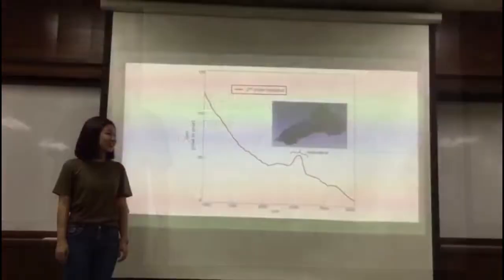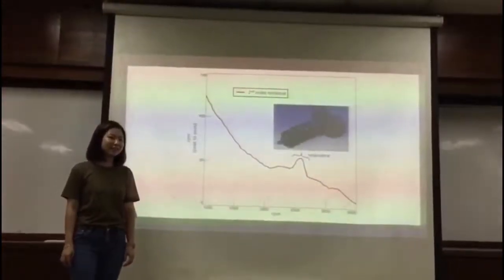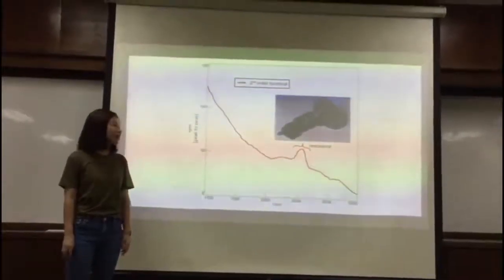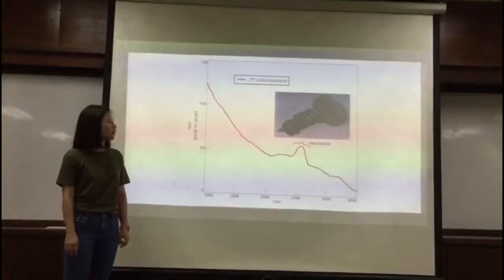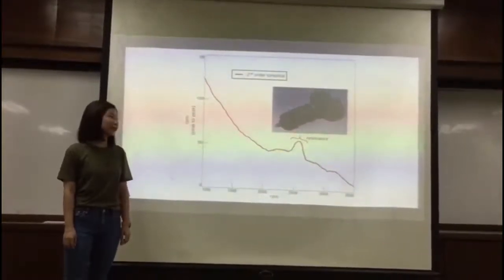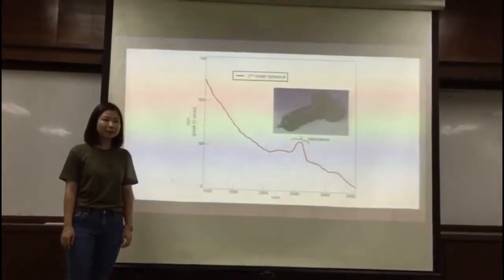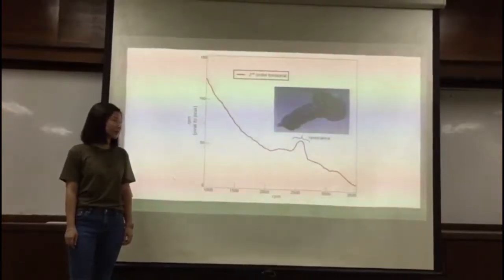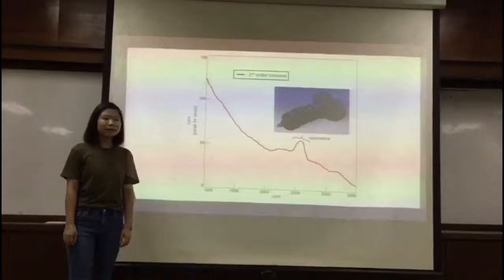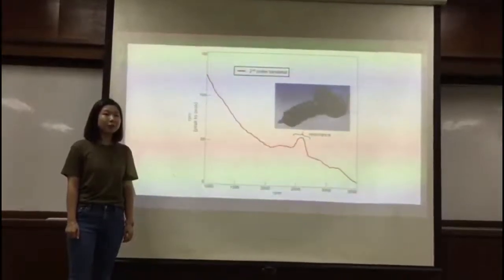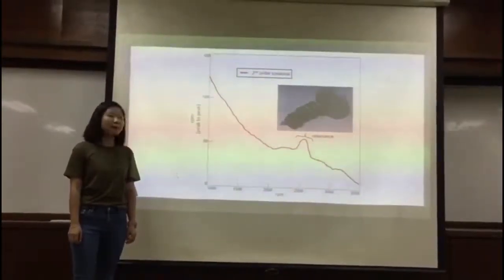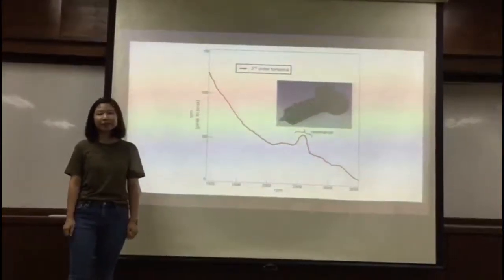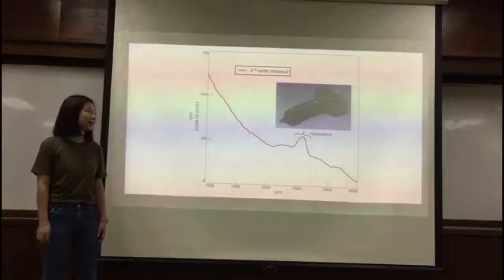So how does the torsional vibration come about? The torsional vibration comes from two loads. First is the gas load. The gas load acts on the pistons and is transmitted to the crankshaft in the compressor. The next one is the inertial load due to the weight of the piston. By adding these two loads, we can find the combined torsional vibrational load in the system.